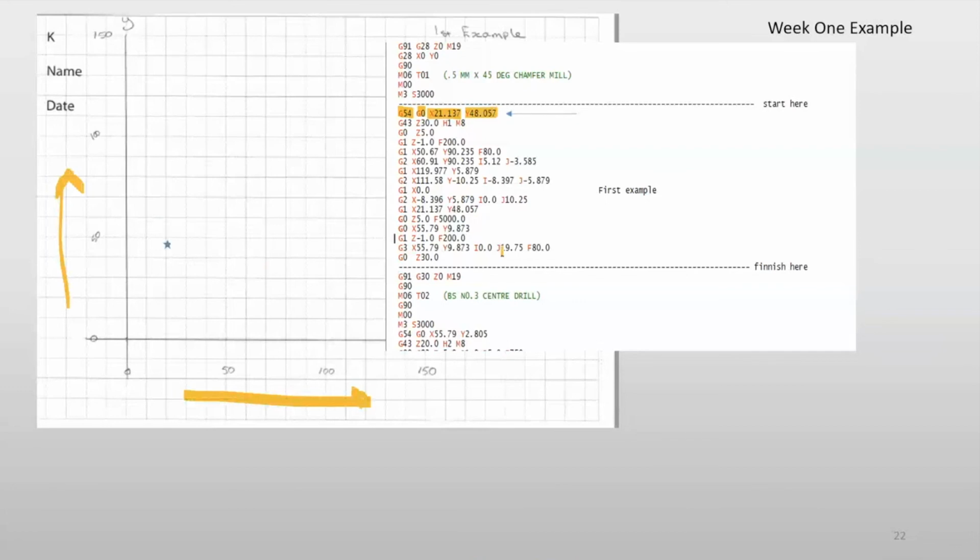The next one does the tool compensation, G43. And in order to do that, to make sure the tool doesn't hit anything, it goes up in the Z. You can see that. I jump in the Z, because it's an XY plane, I cannot showcase it. And then here, I have the G1. What was the G1? Do you remember it?